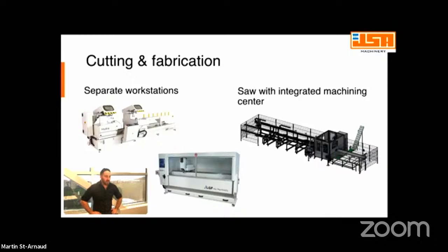So there's been a lot of advance in that technology in the last few years. When the high-speed welders first came out, we were seeing a lack of cutting capacity versus welding capacity. Even in some places they had to get two different saws to be able to feed only one welder, if you're thinking high-speed welders. So now just keep in mind that those technologies are out there. You're going to be looking at also what we now call high-speed saws.